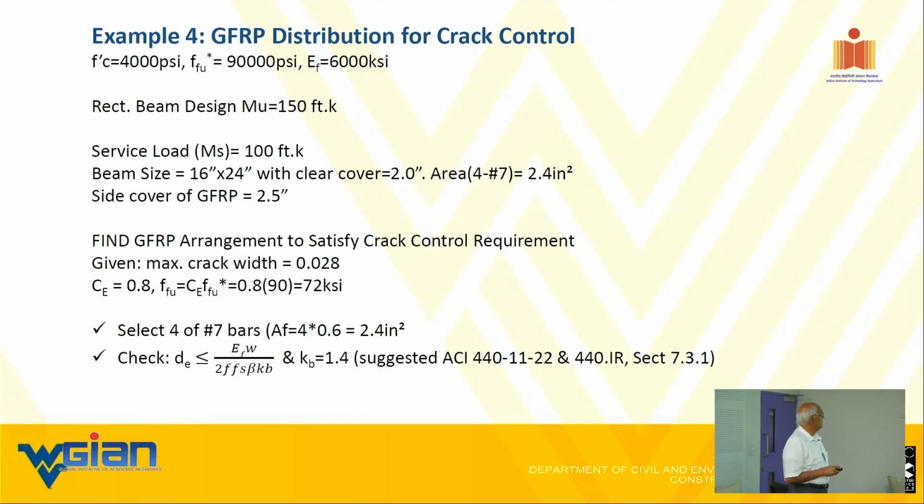Here, the most important thing to keep in mind is the service load moment, not the ultimate load moment. Means what? We don't have to worry about the Mu part, like 1.4 dead load or 1.2, 1.6, those kinds of things.